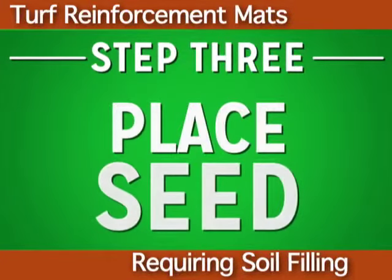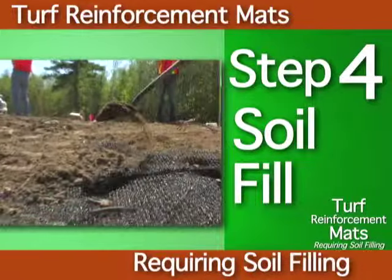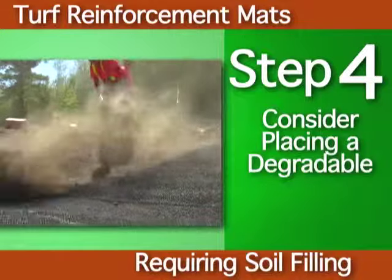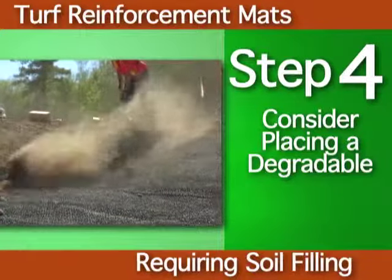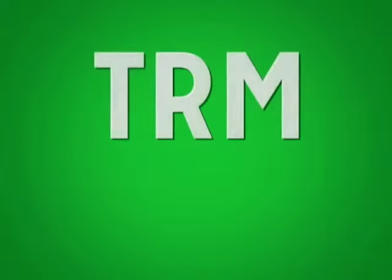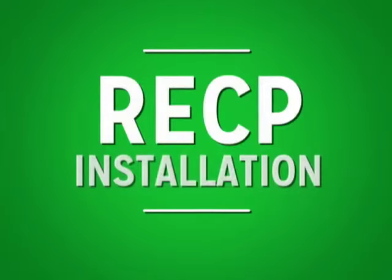The third step is to place seed over top of the TRM. Finally, with the seed down, cover the turf reinforcement mat with soil and consider a degradable RECP to cover the bare soil and accelerate vegetative establishment. Once fully covered, the TRM is successfully installed. That concludes RECP channel installation.